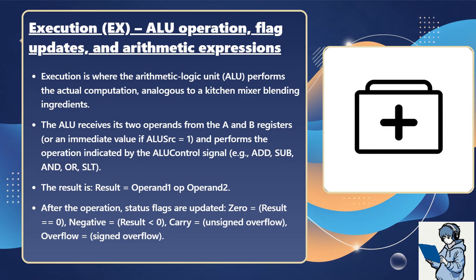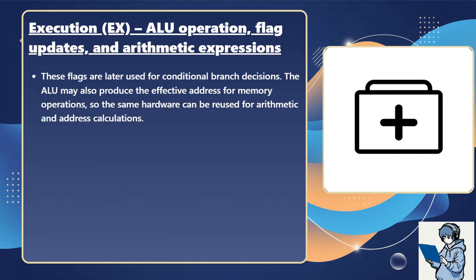After the operation, status flags are updated. Zero equals result equal to 0, negative equals result less than 0, carry equals unsigned overflow, overflow equals signed overflow. These flags are later used for conditional branch decisions. The ALU may also produce the effective address for memory operations, so the same hardware can be reused for arithmetic